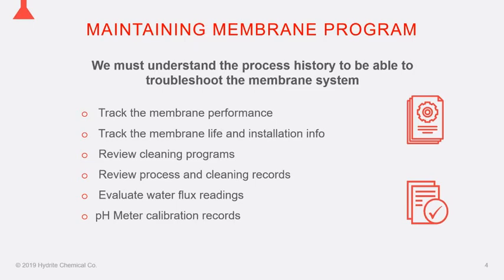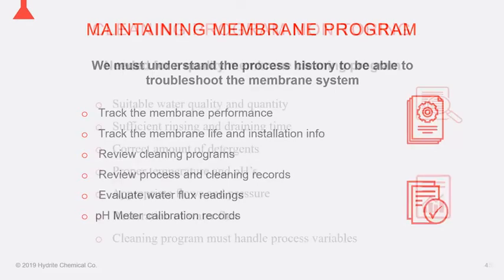A good telltale sign of system performance is the water flux readings, and of course, our pH meter and pH meter calibration. Again, that's the tool that we use for lots of decision making, to ensure that we're maintaining and taking care of those instruments properly.